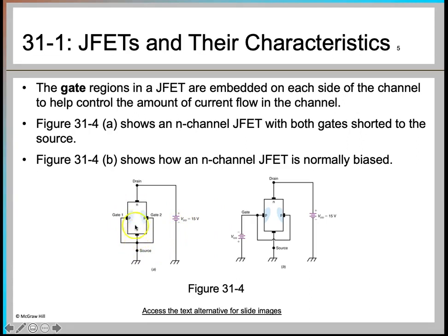And if we talk about the conventional current, which is your ID, drain current, you know that there is a conventional current and there is a natural current. The conventional current is going to flow from drain to source, whereas your natural current, which is basically due to electrons, will flow from your source to drain.